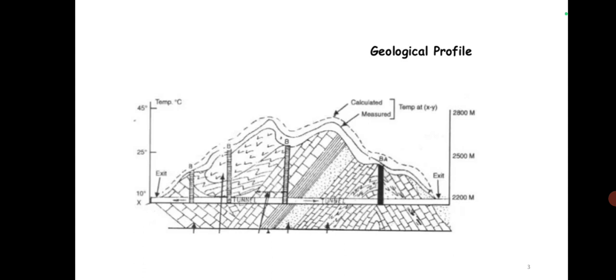So when you are stressing about the rock types, we can see that igneous rocks are competent, but it is difficult to drill. Okay, you may require large machinery, etc., but lining is not required. So that cost of lining you can save, whereas the drilling will be costly. Whereas sedimentary rocks are soft, so easy to drill, but the cost of lining is there. Metamorphic is also similar to granite.